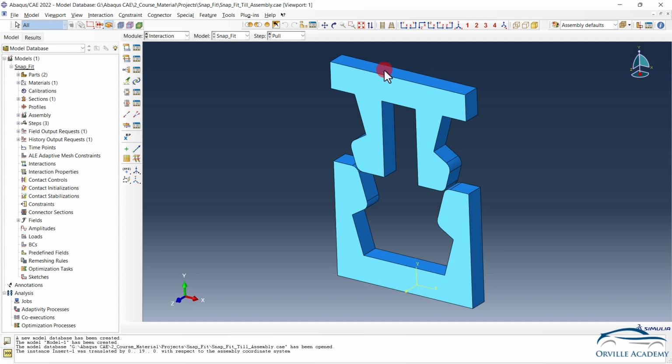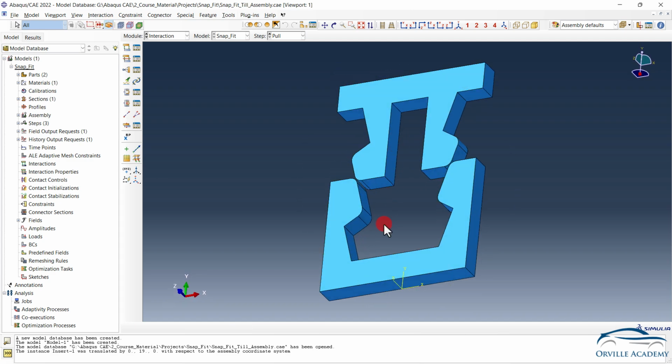If we are applying the displacement in the top face, this insert is going to move in the downward direction. In this space, it will come in contact with the buckle, and then the force will transfer to the buckle. So for the convergence, this buckle needs some boundary condition. So this bottom face of the buckle we are going to fix in all degrees of freedom. So this cantilever extruded part or jaws can move in and out depending upon engagement and disengagement.